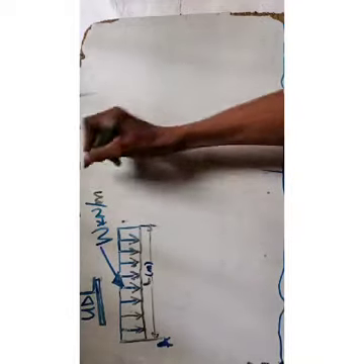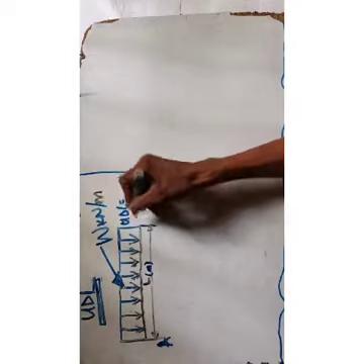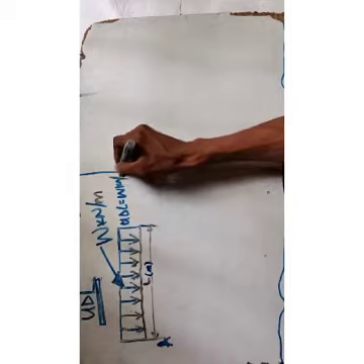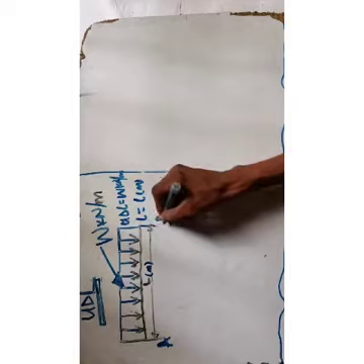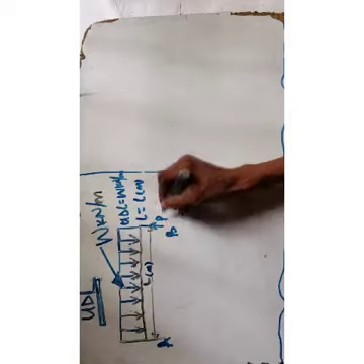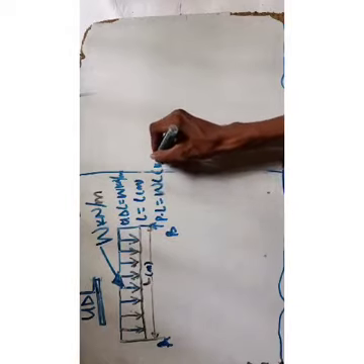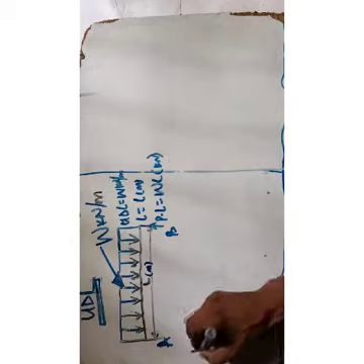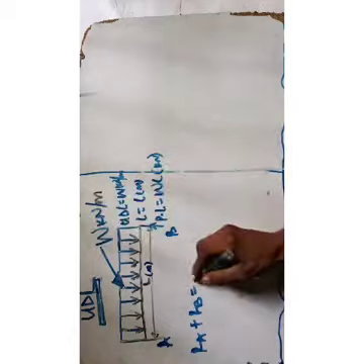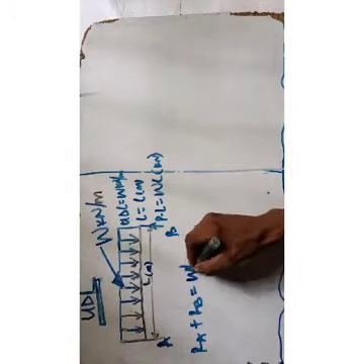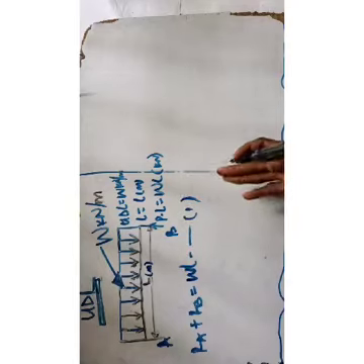So again, you want to resolve this kind of question. What do you do? From your UDL equals W kilonewton per meter. Next thing you have is your length. Your total length is L in meter. Then your point load, this is RB, sorry, this is B rather. Your point load will now be W times the total length, WL, in kilonewton. So now you start with RA plus RB equal to WL, equation 1, converting to point load.